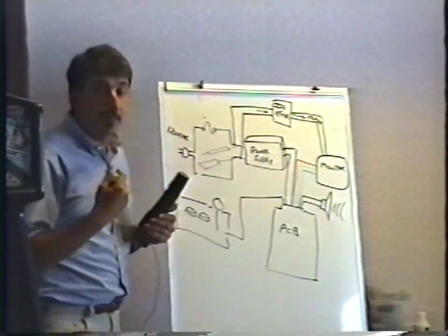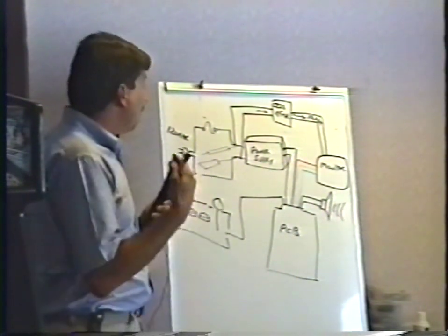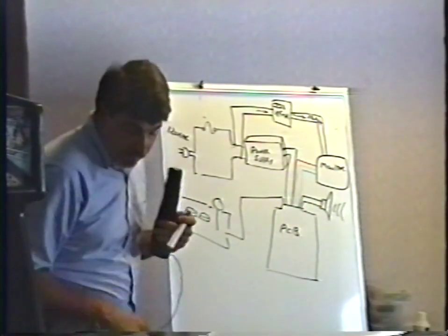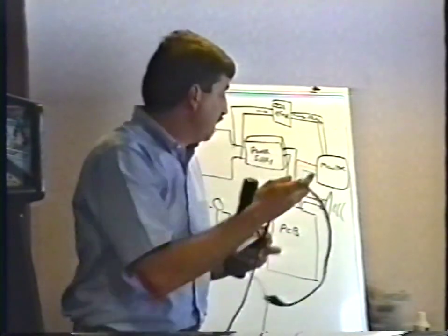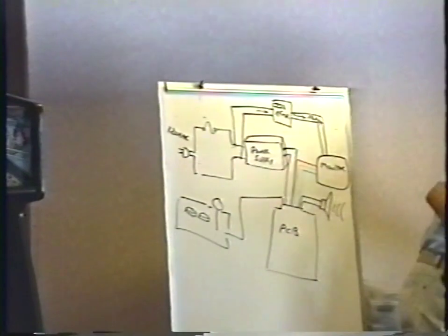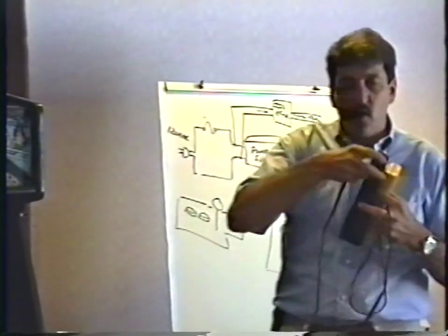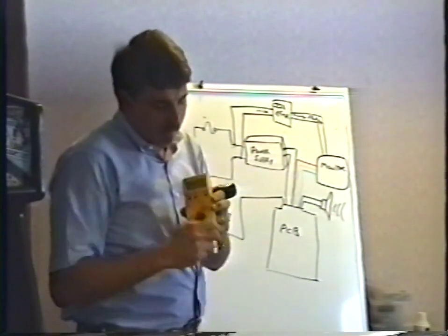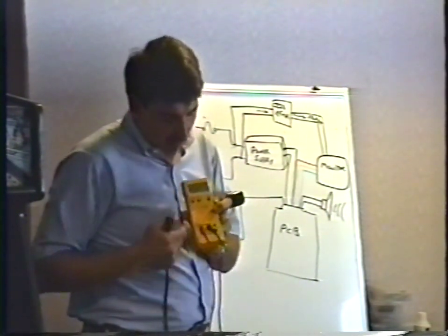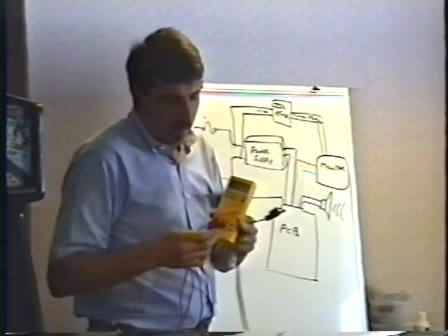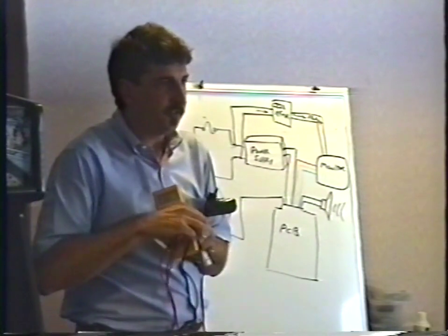That isn't how I do it, because there's a better way to do it with the power turned off, with continuity. First of all, the first thing I did was this, and this is a really fast way that you can tell if the thing is hooked up or not. That is, if the cord is doing anything at all. I put my meter on the continuity beeper or on the ohm scale, whichever your meter happens to do, where it makes a beep, just for the sake of discussion.